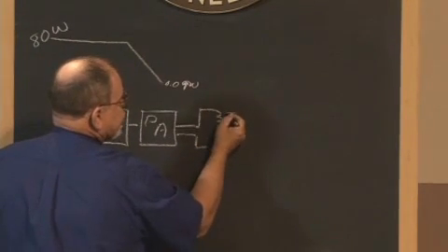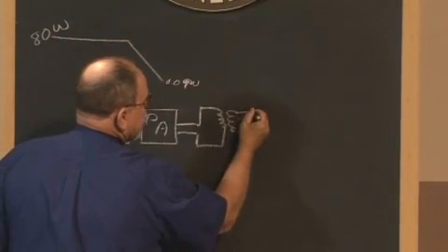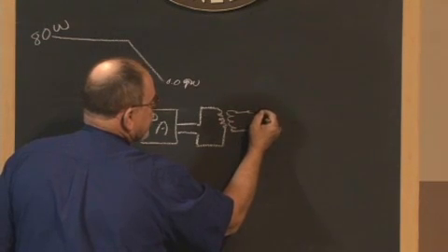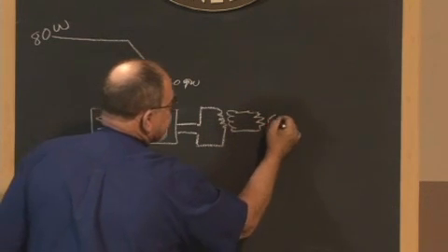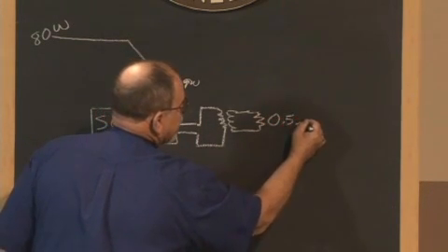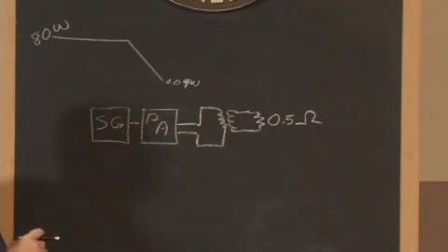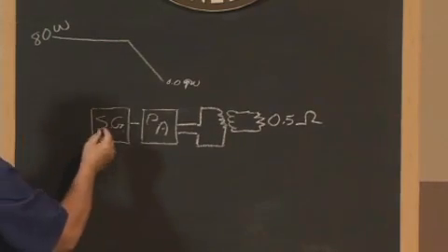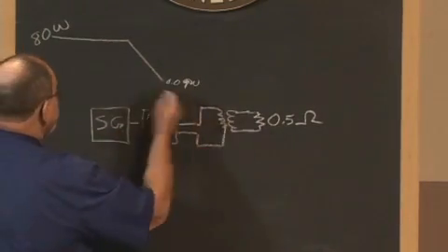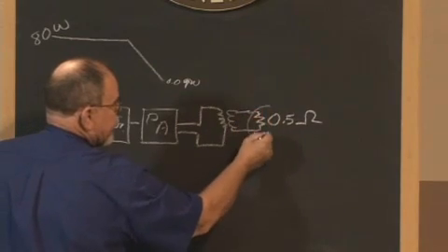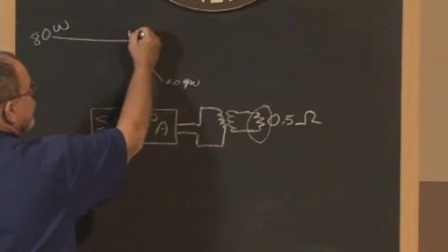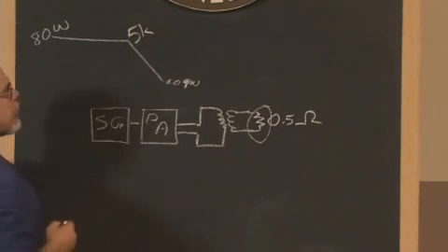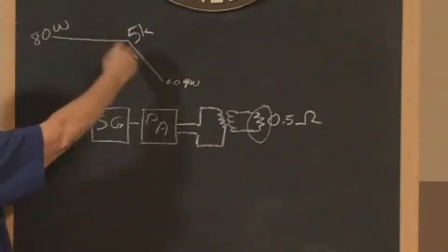The secondary of the transformer is connected to the resistor that is set for calibration, and that is 0.5 ohms. This is basically the test circuit used for calibration. We generate a signal and apply power to where we dissipate 80 watts in that resistor. And as the frequency goes up, this breakpoint occurs at 5 kilohertz. And then we start diminishing this.